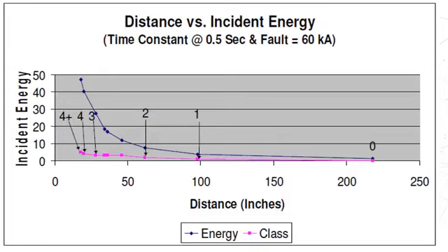Unless that task is already justified to be performed live. There could be a scenario where you have performed an inspection at 36 inches by wearing PPE of 10 cal/cm². Now you raise that some rectification work needs to be performed. That work does not fall under the exemption criteria of Article 110.4.